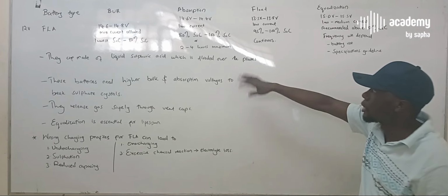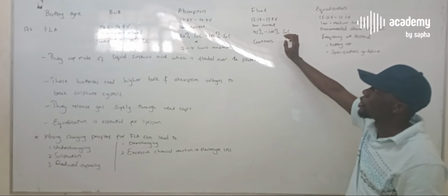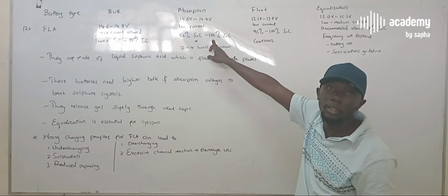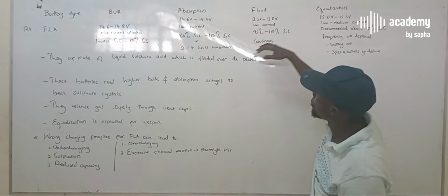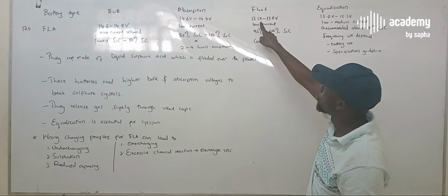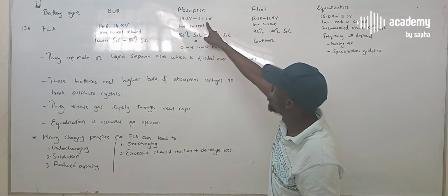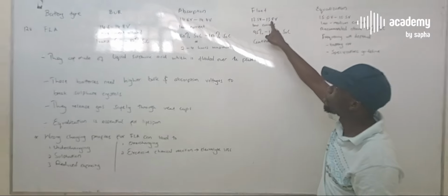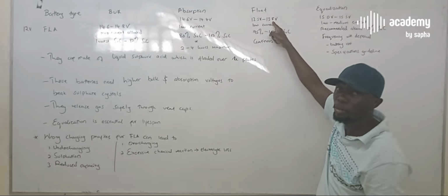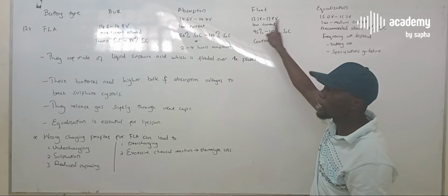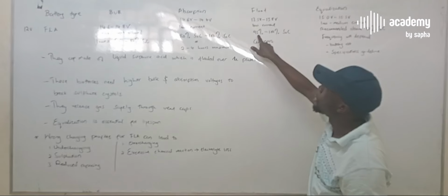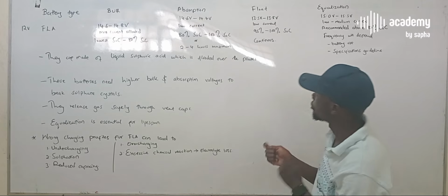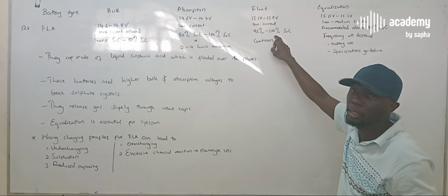The third stage now is the float voltage. This is after the battery has hit the 100% state of charge. So here, we lower the voltage again from 14.4 to at least 13.5 to 13.8 volts. So again, here we utilize low current, and the battery itself will keep shifting between 95% to 100% SOC.